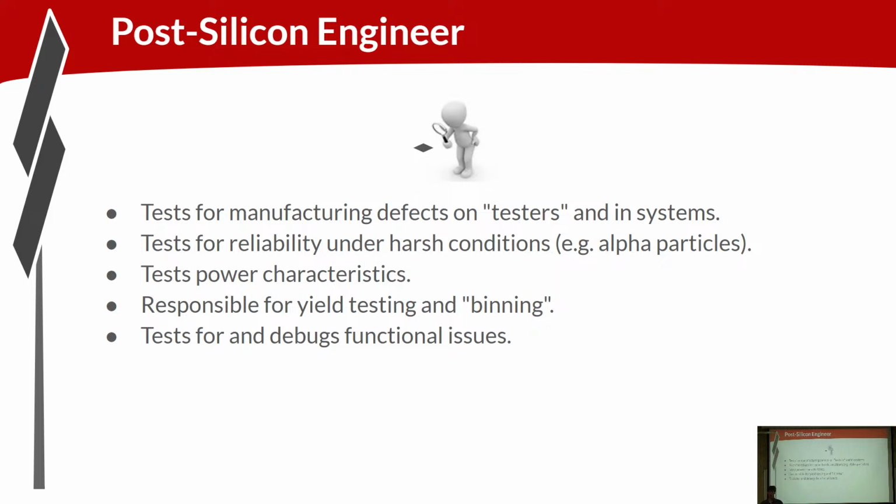And also the clock speed of the chips, right? So we'll crank up the clock on these parts and see where they fail and then back off a bit and bin it appropriately into a particular clock speed bin, right? So over the course of my career, the binning strategy has gone from no strategy, it's one chip, it's one product, to incredibly complex binning strategy that involves multiple people to sort the whole strategy out alone, and then, you know, more engineers to execute on that strategy post-silicon.